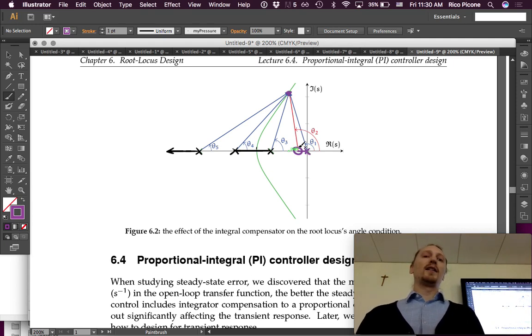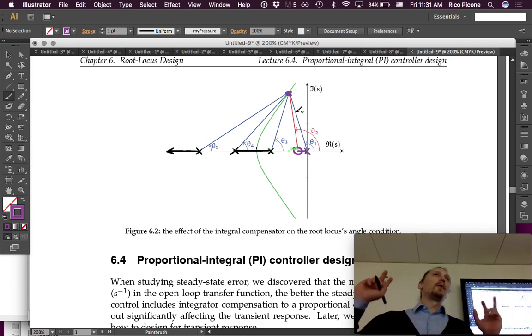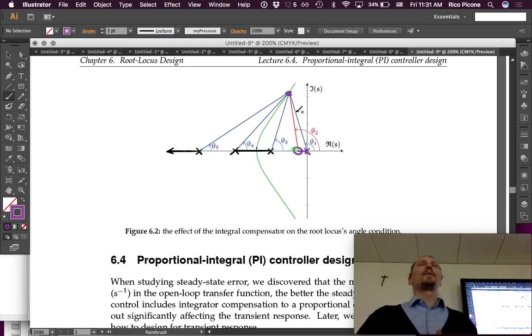But poles that are close to the imaginary axis are significant to the transient response, well, to the response as a whole. And we are introducing one here that is most likely going to be closer to the real axis than those, so we hopefully have dominant poles, right? So that is a real effect, and we'll see how that effect manifests itself in the example.